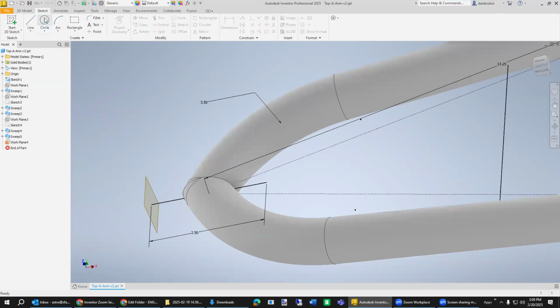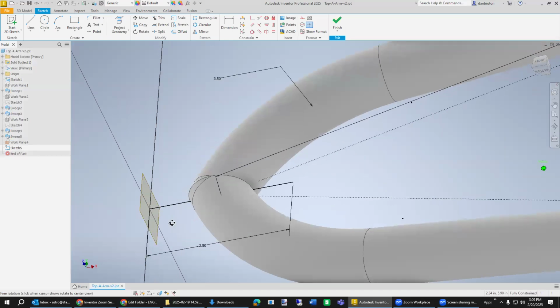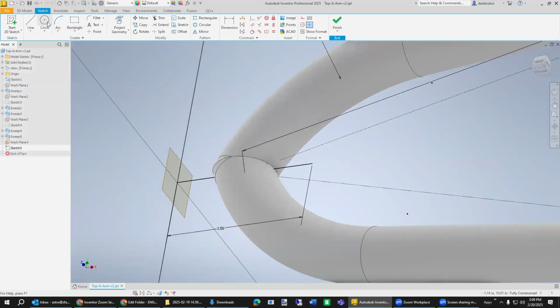Might as well select the circle and then highlight this in green. There we go. Can draw the circle at this point. I'm not sure if I hit the middle exactly, so I'm gonna hit escape. Maybe orbit around just a little bit, so make sure I can lock in to the center. Snap to that, go out to here.